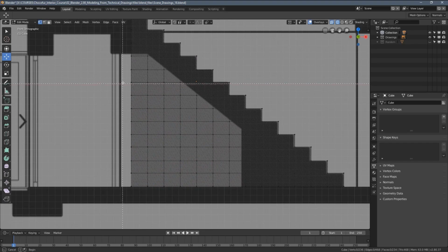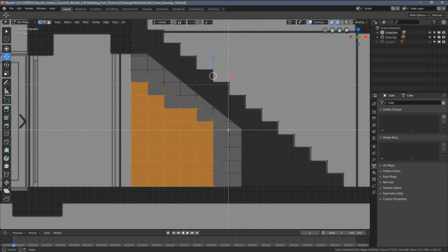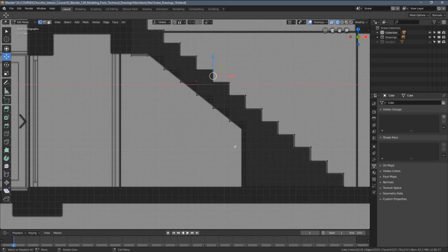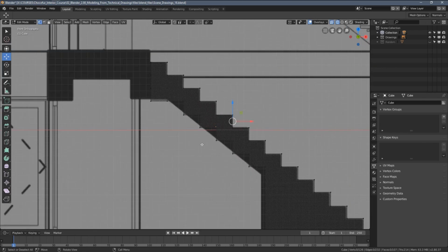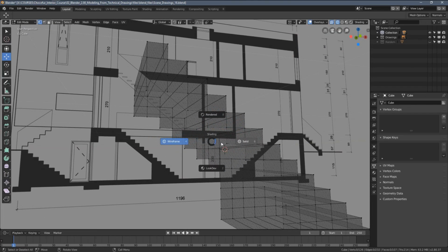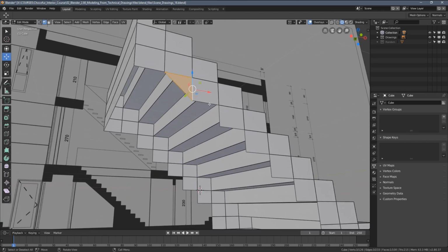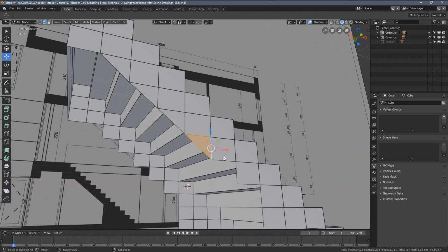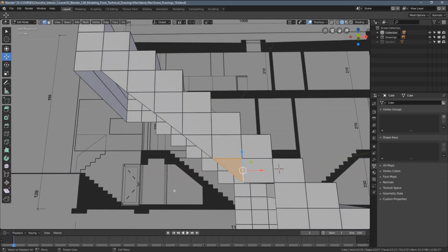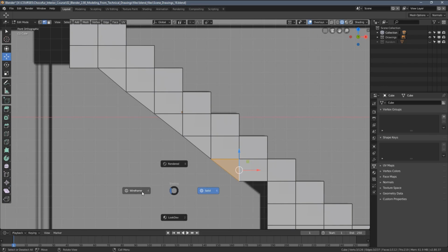And yeah, let's move into the modeling. So as in the previous example, I will just select all of the unnecessary vertices and remove them. And again, you can do this step by step if you're not sure if you're deleting the right ones. We will now select those edges and just press the F key. As you can see, it fills those areas with nice triangles.